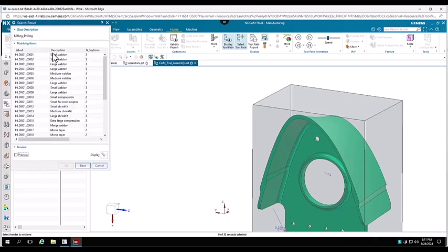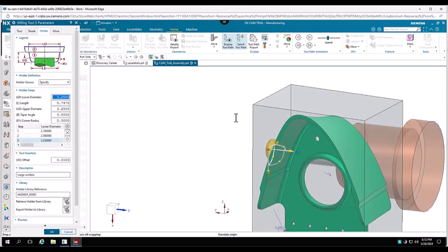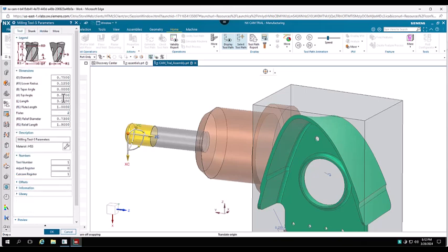Select OK there, and I'm just going to grab this large golden shank and display that, and you'll see that I now have a holder with my tool. So click OK there. Drag this back over here so we can see it. So let's say you wanted to have the tool represent the full length of the tool that's up inside the holder there. You can do that as well. Go to Tool, and we'll just say we'll add another inch to the overall tool, make it 4 inches.